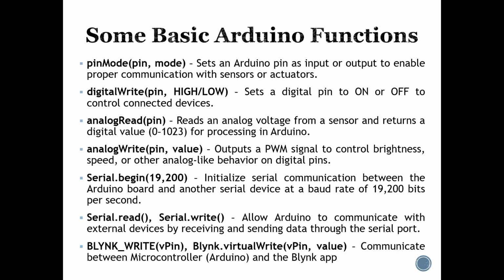Also, I used several fundamental Arduino functions like pinMode to configure pins as input or output, digitalWrite to set a pin high or low, analogRead to read sensor values, analogWrite to generate PWM signals for brightness or motor control, delay to add time gaps for timing control, and Serial.begin, Serial.read, and Serial.write for serial communication. These functions were the building blocks for the project code.